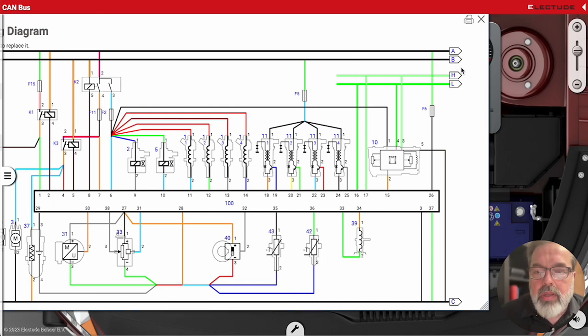So anytime you're looking at a wiring diagram and you see these arrows, that's basically showing you a page break. We're not showing you where these two items go, but you'd have to look up in another wiring diagram the other ends of these two. That's not a splice, that's just a page break. And somewhere else this wire would continue and go to other modules on the car.